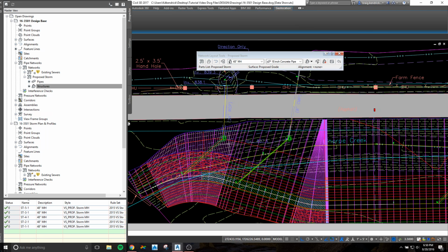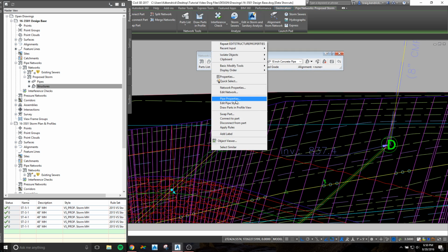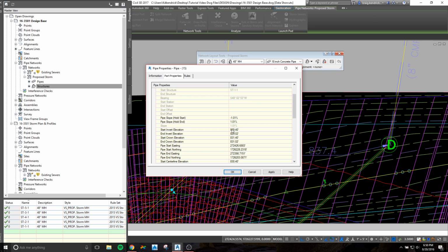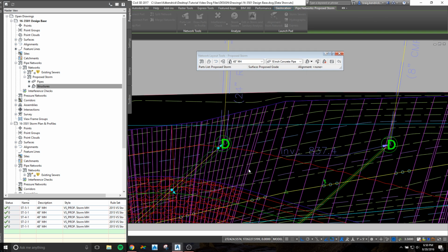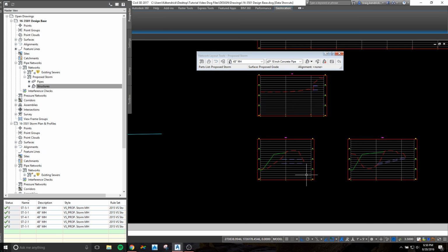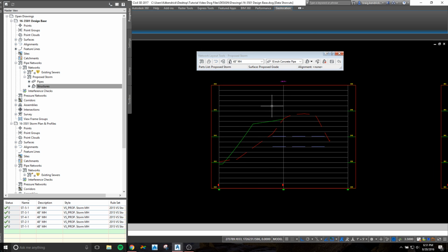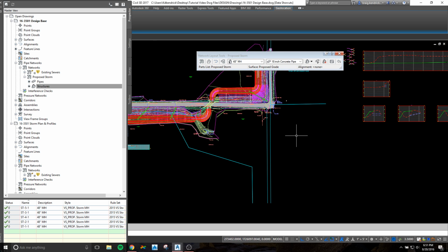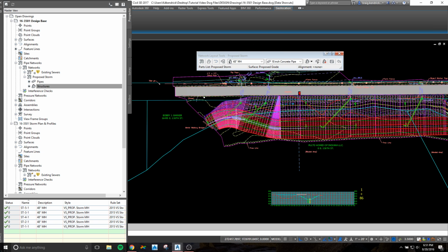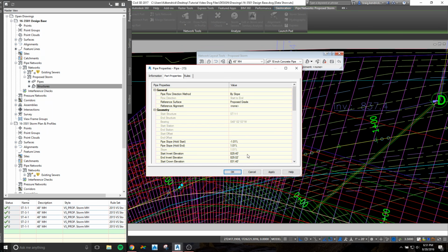Alright, so I have preliminary stuff set up. I haven't even begun to look at elevations of how the pipes came in elevation wise. They came in at 829. Without looking at the profile, I don't know where that is in relation, so we can run real quick and look at this profile. They came in a little low for this profile. This is the line ST1 profile, so we can come over here and we'll make it 835 for a starter.